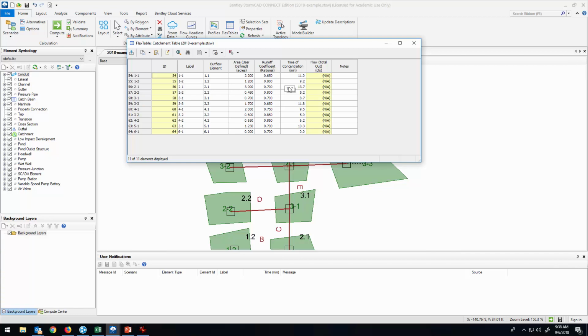Well, you'd have to go out to the site and maybe observe it when it's raining and actually try and track a particle as it flows from that furthest point of the watershed towards the outlet. Or you could use one of the methods like kinematic wave or NRCS, methods that can estimate the time of concentration based on the physical features like slope, rainfall intensity, roughness, and so on.